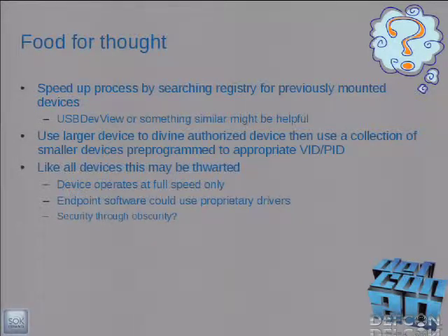One other thing: who remembers what the maximum packet size is for a full speed USB endpoint? 64 bytes. What is the default block size? 512. So what happens is it has to fragment and unfragment all those blocks. That does give you a little bit of a performance penalty, unfortunately. But I don't know how you could do anything better other than find something that supports full speed.